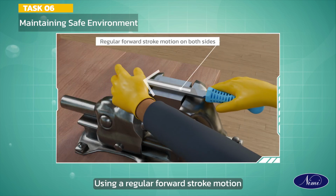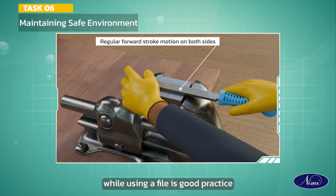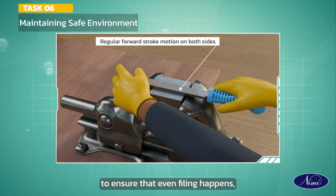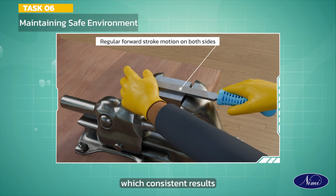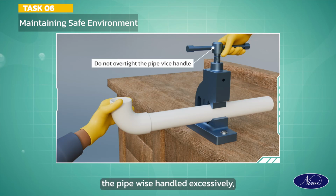Using a regular forward stroke motion on both sides of the workpiece while using a file is good practice to ensure that even filing happens with consistent results. Tightening the pipe-vise handle excessively while cutting a pipe can lead to the pipe breaking or becoming damaged.